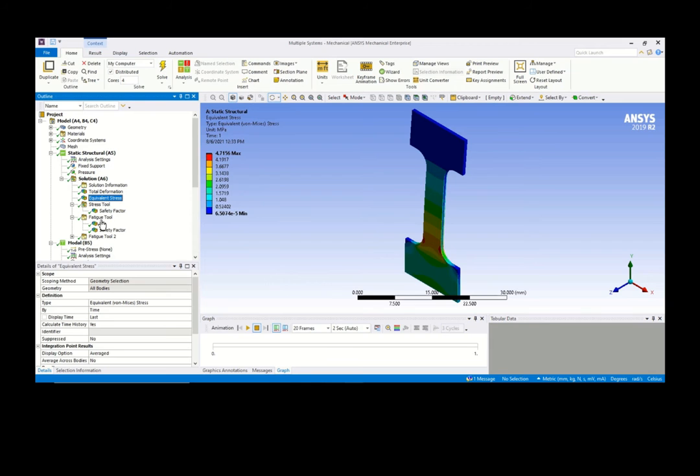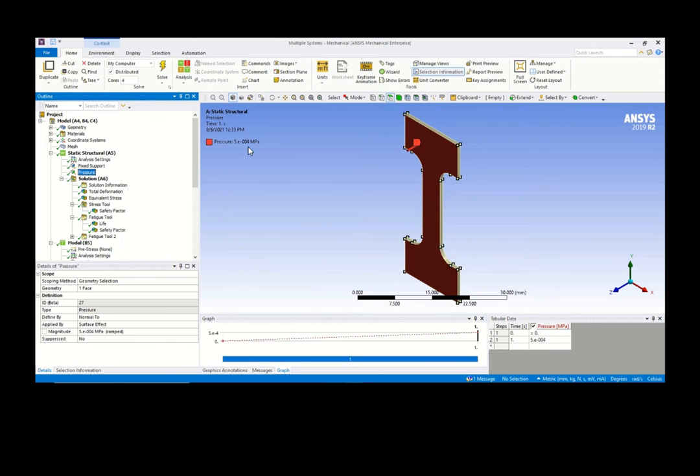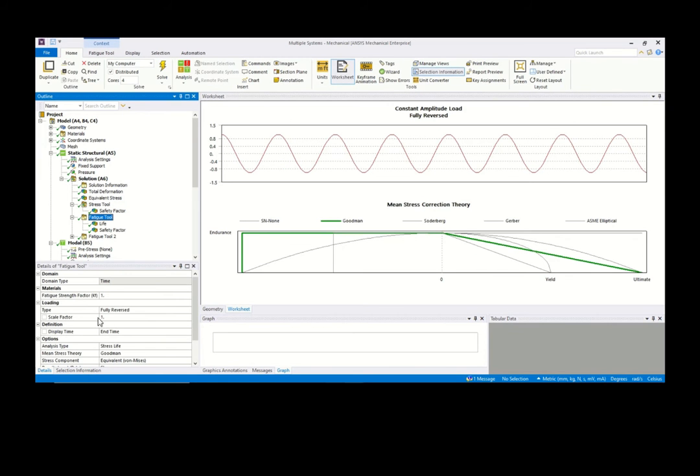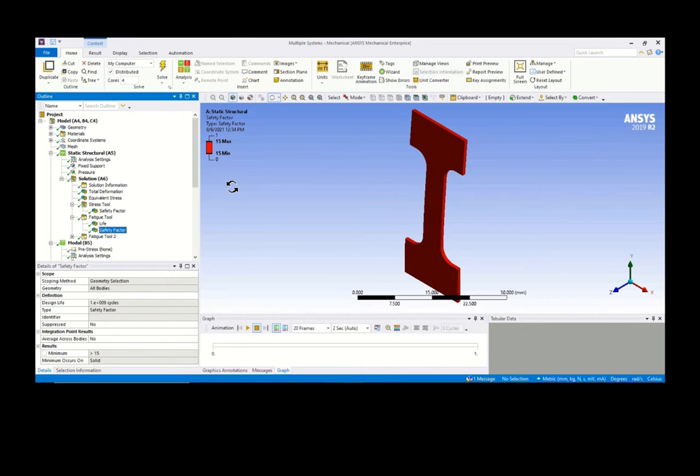All right. In the fatigue analysis, if you still remember, we assumed this equivalent stress caused by this static pressure of 500 Pascal, which is 4.71, now becomes completely reversed. So under fatigue analysis we put a factor of -1. We are assuming that this static pressure of 500 Pascal will induce a dynamic stress of 4.7, negative 4.7, 4.7, negative 4.7. In this case, the factor of safety also shows 15 and above, no issues.